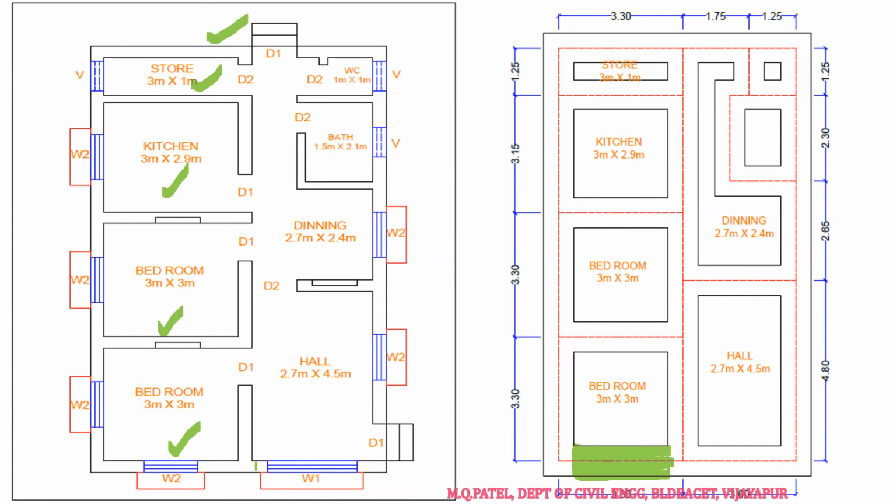Next we'll go to this second wall. I'll take this as short wall number 2; this one I had taken as SW1. Again we'll take the center to center distance. The clear distance is 2.7 meters. The center to center distance will be 3 meters. Why? Because 0.15 by 2 plus 0.15 by 2. So therefore the center to center distance will be 3 meters, right?